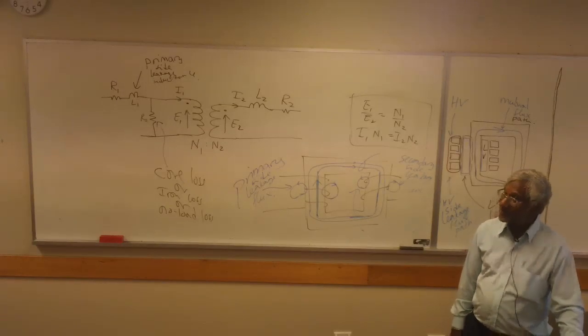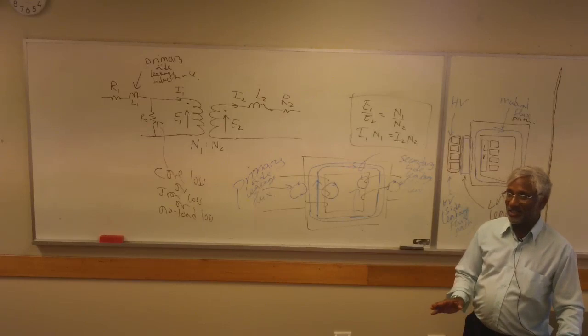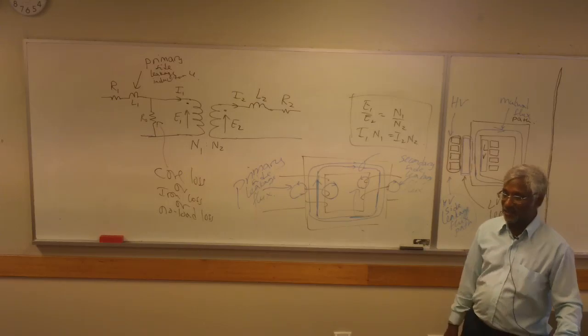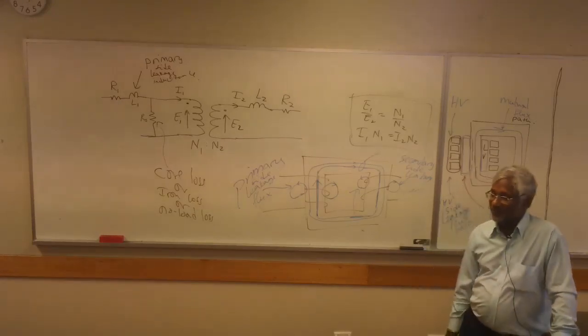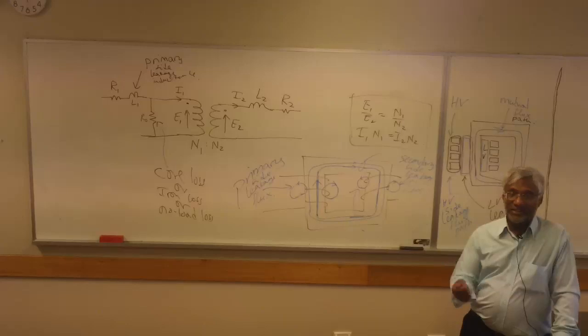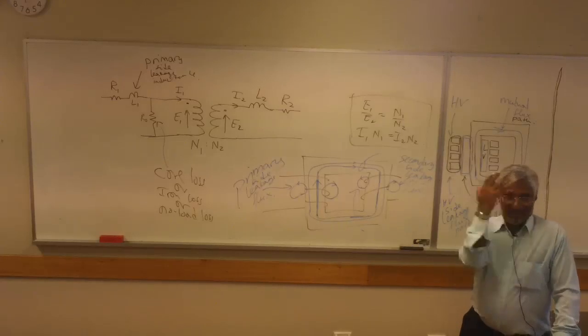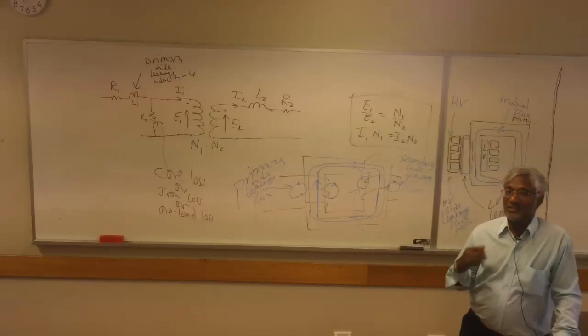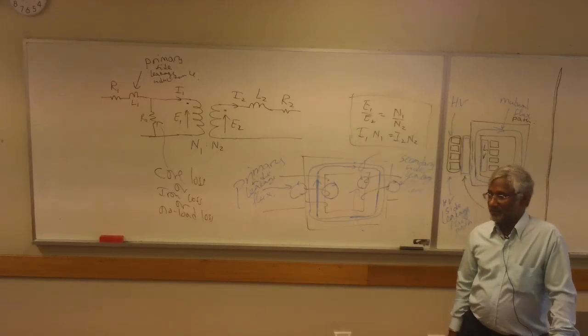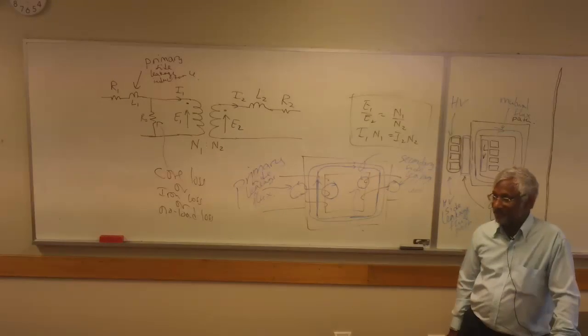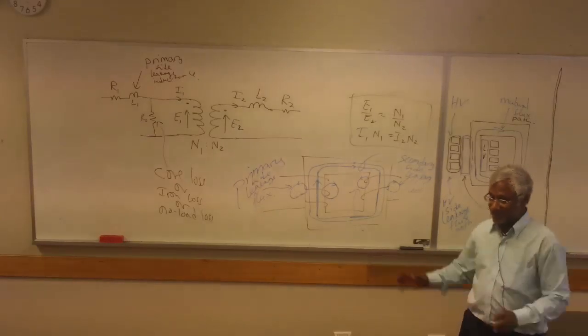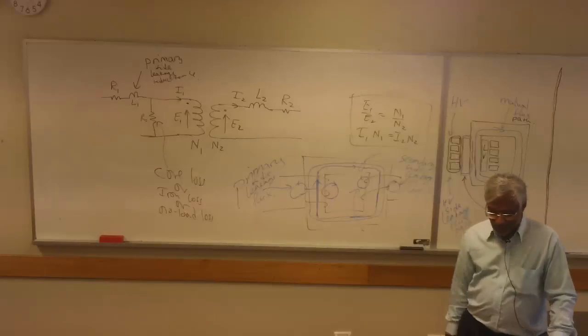Inductance material? No, again, our language: inductance is not a material property. Reactance is not a material property. Material properties are like density, conductivity, resistivity. These are material properties. That's right. So what permeability would you be asking for if you wanted 0 magnetizing current? Infinite. That's right.